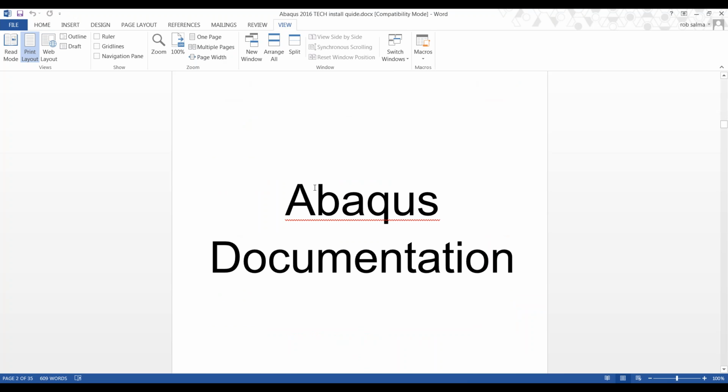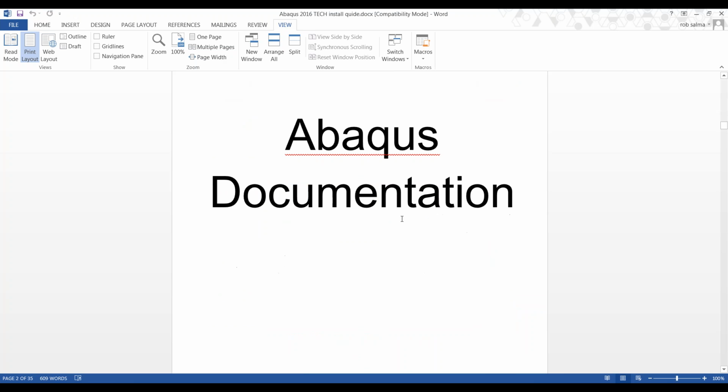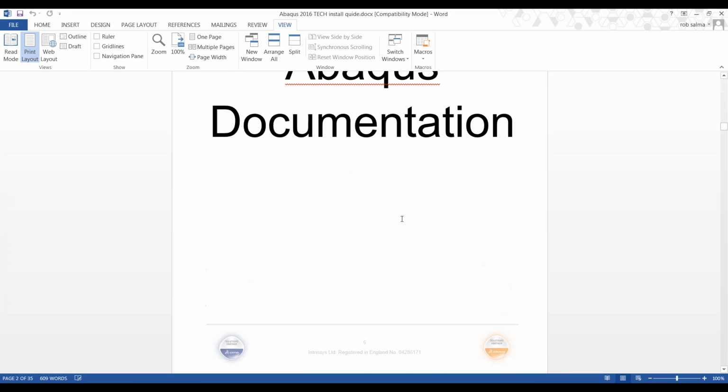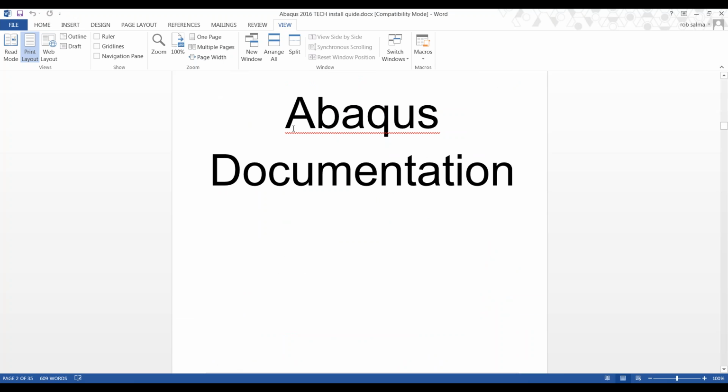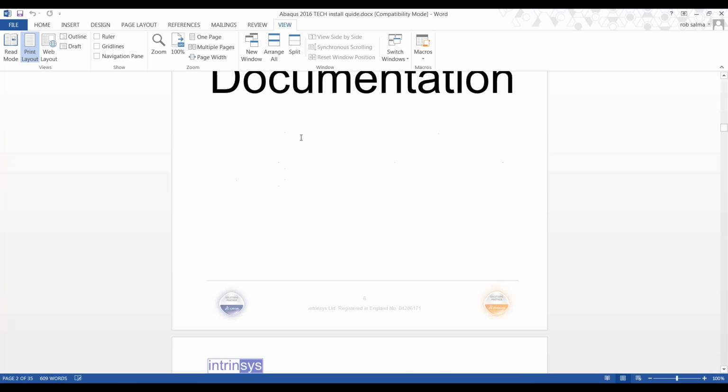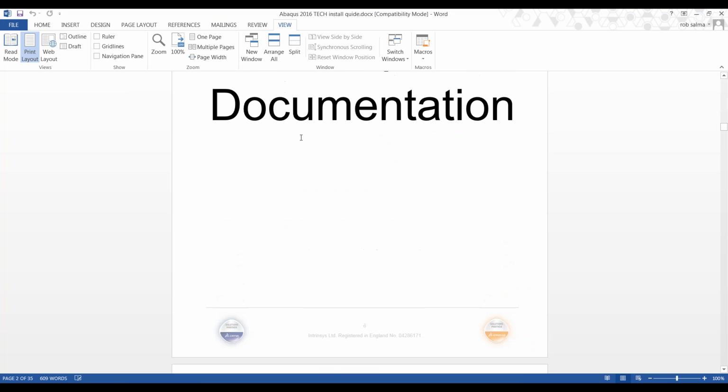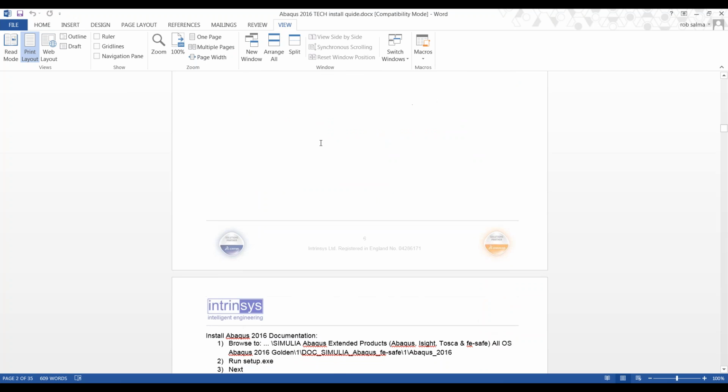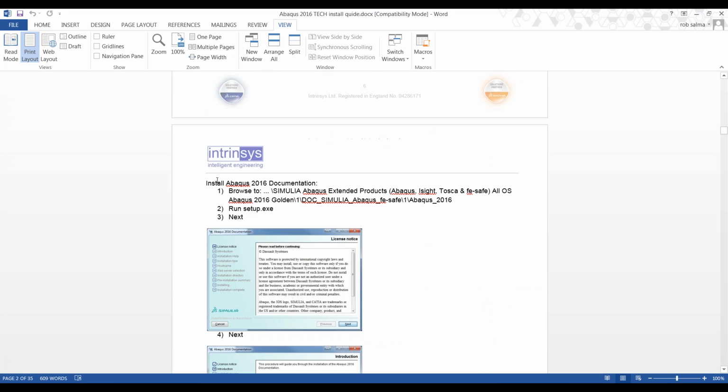We then, just like before, go on to install all SIMULIA documentation. That's the help files essentially. The reason we install them first is because when we go to install Abaqus, it will pick up any web services that are running for the documentation. If we didn't install the documentation first, it's not too much of a problem, it's just not recommended. We'll have to go back and manually associate where the documentation is found in the installation, which is a bit more of a pain.